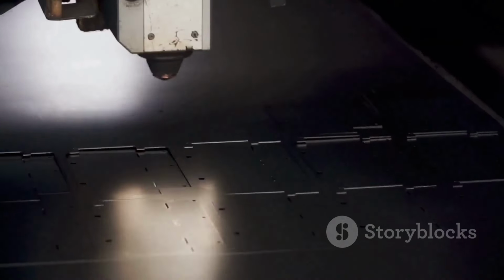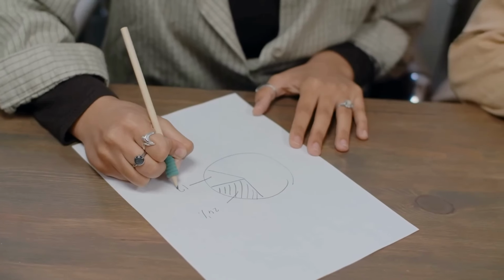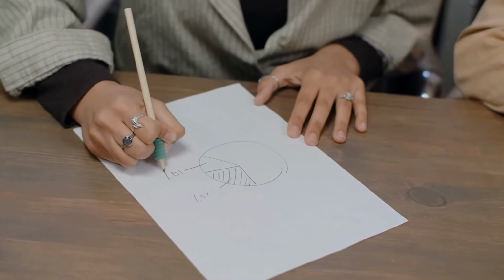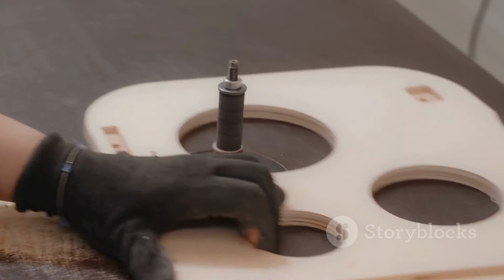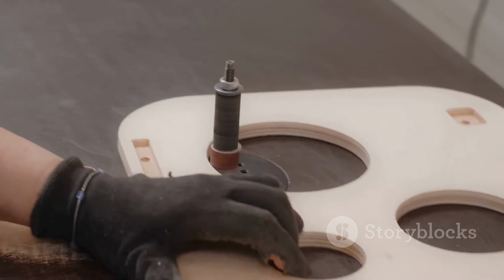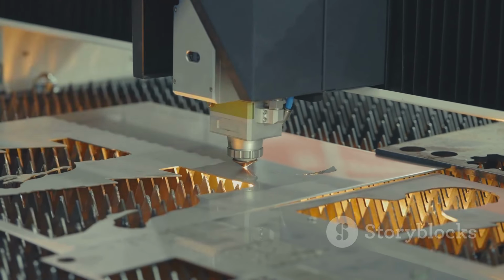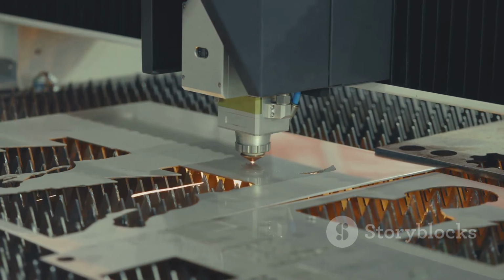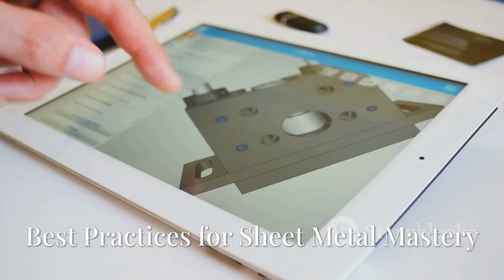Create a separate sheet metal part for the lid. Sketch a rectangle slightly larger than the box's opening to allow for the lid to fit snugly. Use the Edge Flange tool to create flanges on the lid that will interlock with the flanges on the box. Finally, use the Flatten command to generate the flat patterns for both the box and the lid.